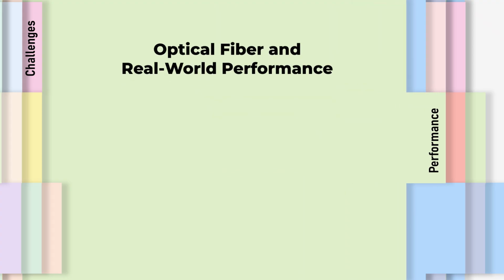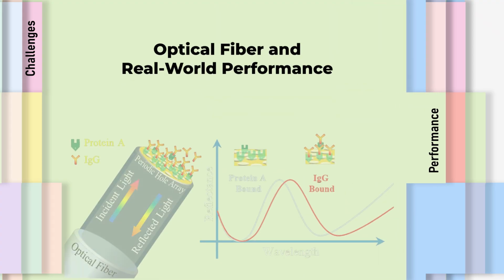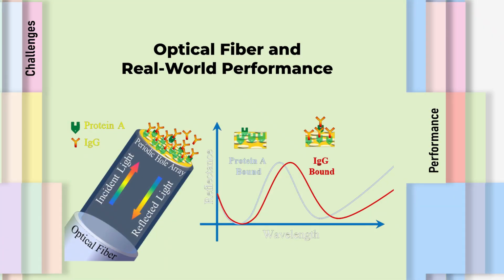Optical fiber and real-world performance. Optical fiber-based sensors operate using total internal reflection. For total internal reflection to occur, the refractive index of the core must be greater than that of the cladding, and the incident angle must be greater than the critical angle.